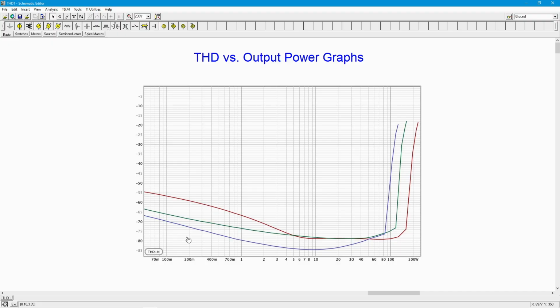For very small signals, noise plays a bigger role, right? A noise floor is a noise floor. It's a bottom level. So the smaller the signal is, relatively speaking, the noise is higher, right? You're getting closer to the floor. That might be part of this. I don't really know who made these amplifiers or the kind of circuitry they're using, but that's one possible answer. The other thing is, depending on the topology of the amplifier, you'll see different things.